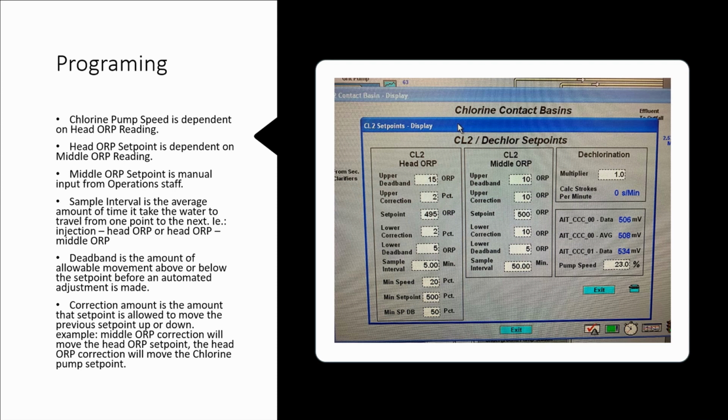So again, there's variances at every wastewater plant. You see that flow go up and down during days and nights. So we take the average, and that's what we use there. And then we've got some things in here like minimum speeds. We don't ever want to see our chlorine pump go below 20 for the speed on the chlorine pump. Right. Because we know based off our experience with our facility that below that becomes problematic with meeting our E. coli